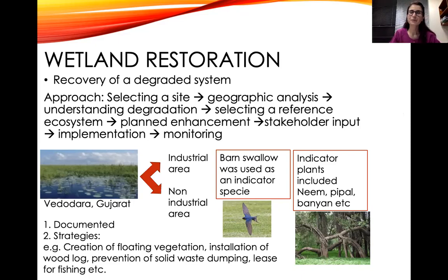Yeah, the groundwater. So like I said in the beginning, oftentimes if the soil is contaminated, the underground water is also contaminated alongside it. So when you say wash, pump, and treat, it refers to that particular system where you're washing all of it from the soil, extracting all the groundwater, bringing it to the surface, treating it there because it's difficult to treat contamination in groundwater, and then put it back.